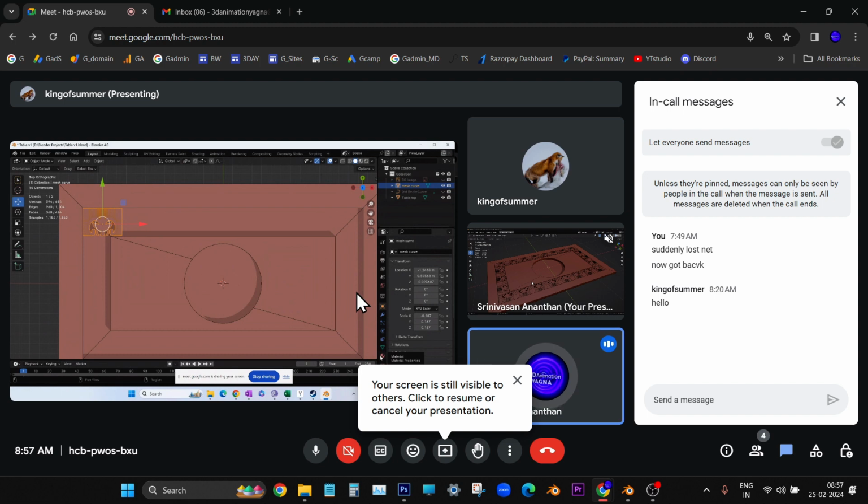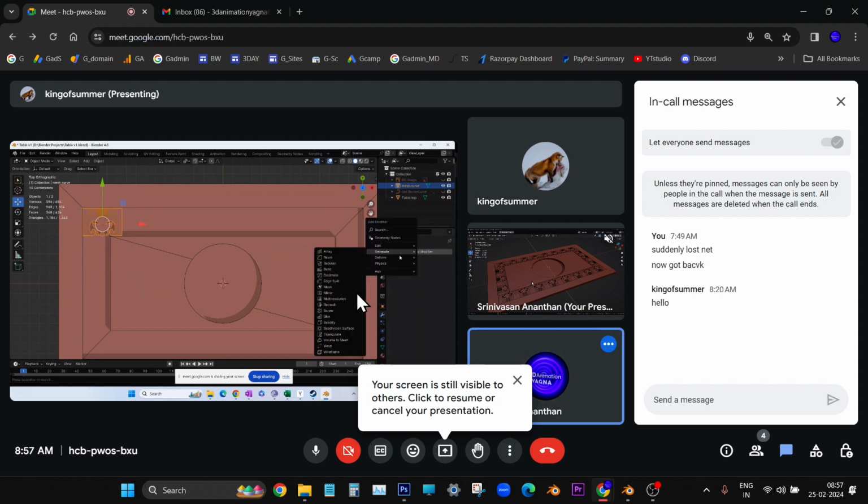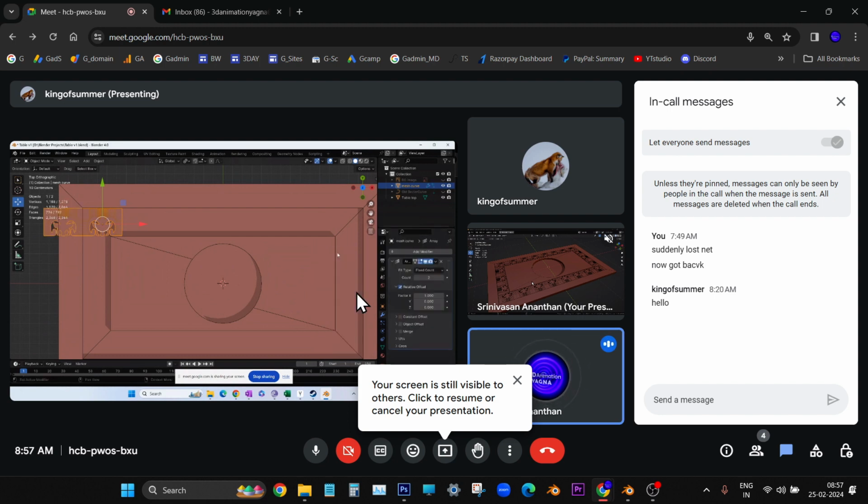Go to modifiers and add modifier, generate array, first option. Yeah. Now you don't have to move anything, it will replicate by itself, but it is replicating that side, I don't know why. Maybe you have to put factor in factor x, no, -1 you put in the settings, -1 below factor x.